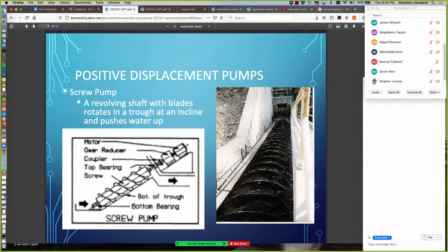These kinds of pumps are in use. They're more common than you might think. They're really good in flood control and hurricane systems because they can be left alone, turned off for long periods of time. As long as there's a monthly visit to check that the bottom bearing is still functional and bump the motor to be sure nothing is seized up, they can be turned on when they're needed.